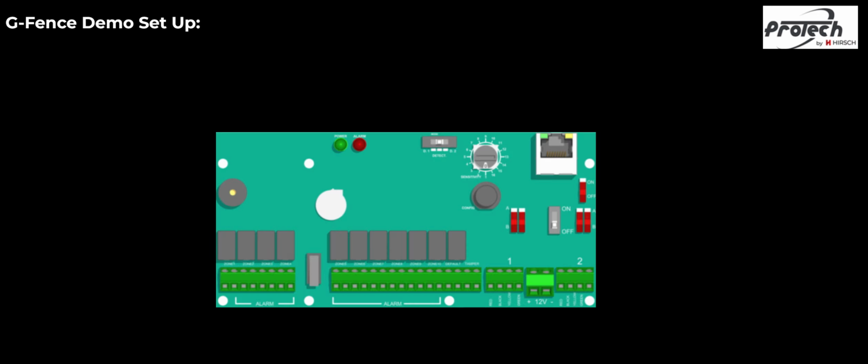If you do not have your demo set up yet, let's go ahead and get that set up. We're going to need to connect some power to it. And then once we have the power connected, we can turn on the power with the white switch, putting it in the up position. To turn on the interface, you need to have the single red dip switch in the up position.